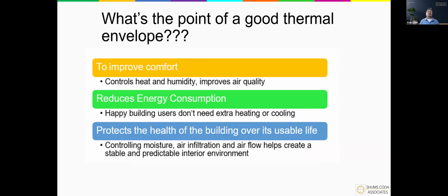One thing that we do is then the building acts in the way that we originally designed it to be used in, right? That includes heat, humidity. We're not over humidifying the air. We're not adding additional heat that we don't need. And the systems that are designed to be efficient for that system, for that building, are going to be able to work as well in that environment when it's sealed off properly, right? So that's our sizing of our mechanical components through things like our Manual J and D.